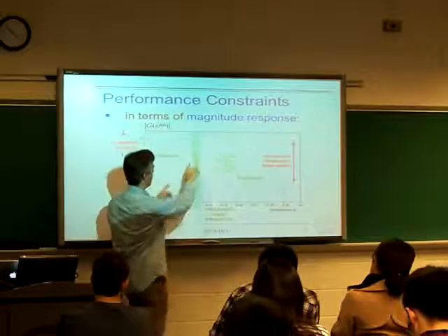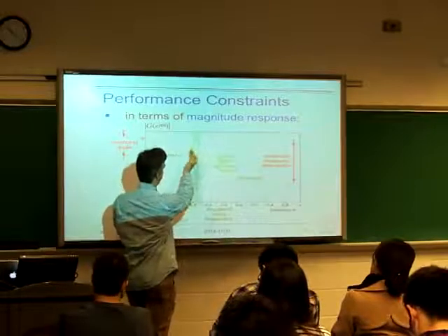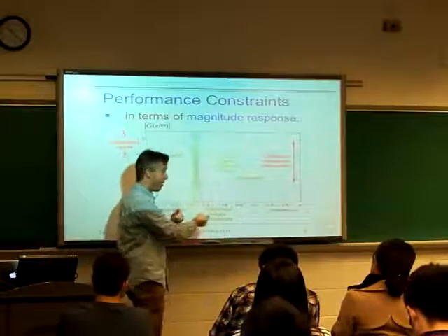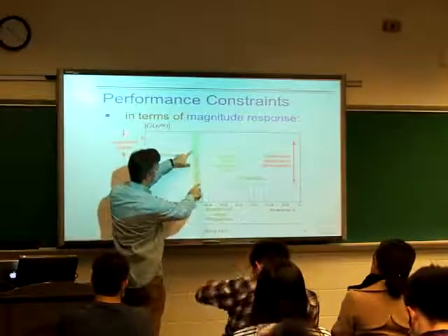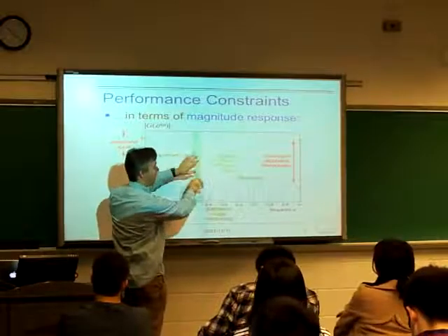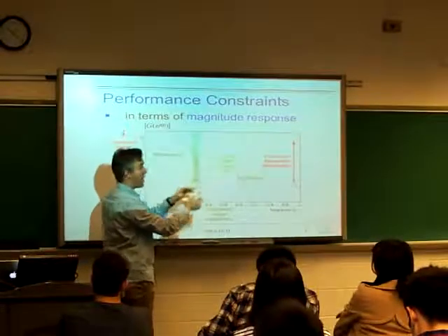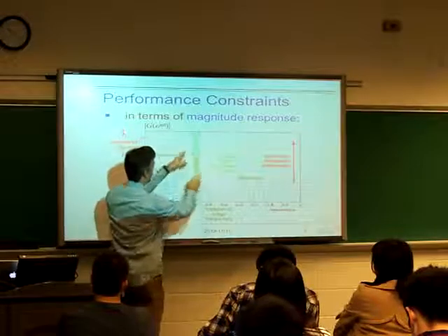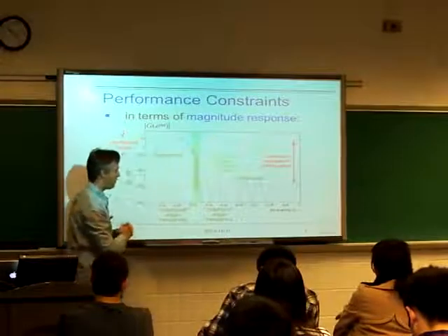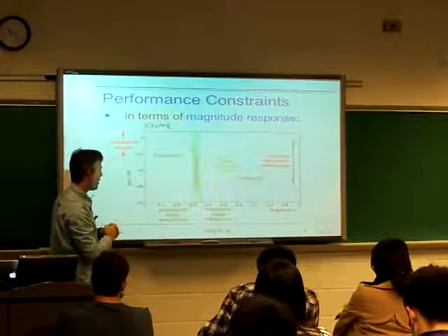And so somehow the filter we're looking at is not the absolute optimal one. Or, alternatively, if it was here, then you could move the passband edge up a little bit and you get a narrower transition band, which would mean a better filter. So there's nothing necessarily magic about these points, but typically if you've specified it, then the specification will involve pushing out your limits so that those points touch there. We'll talk more about that later.